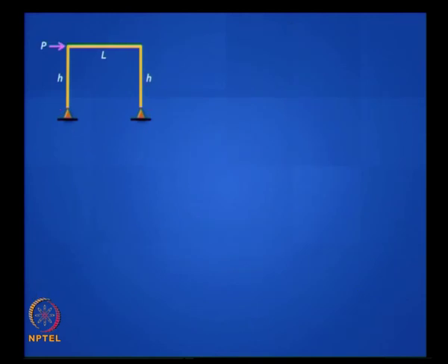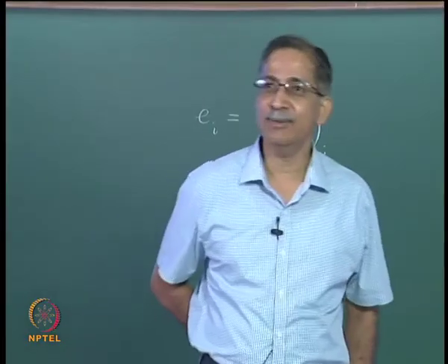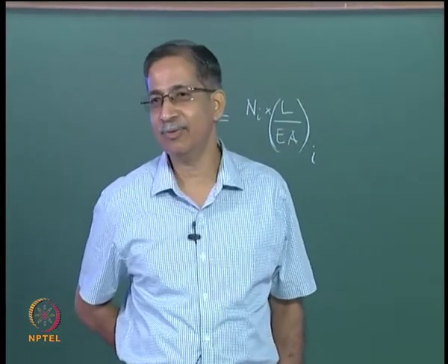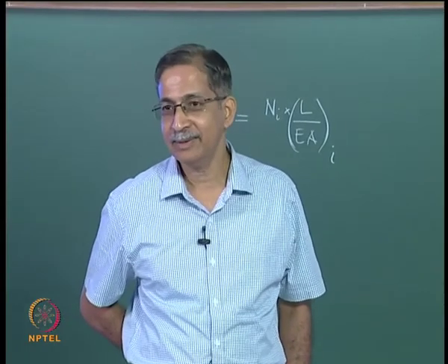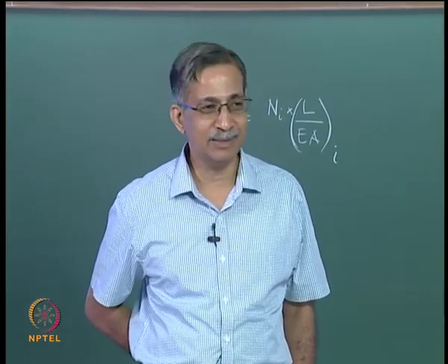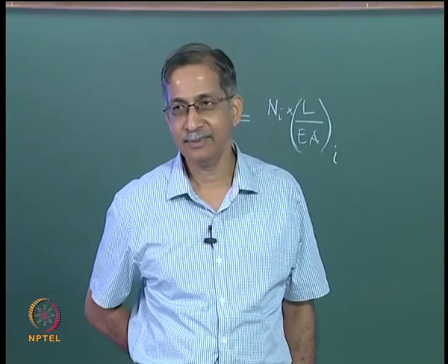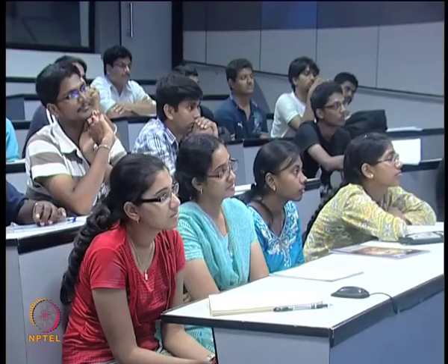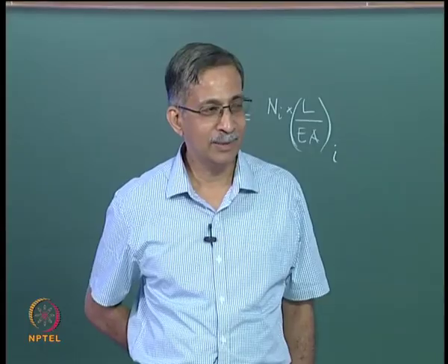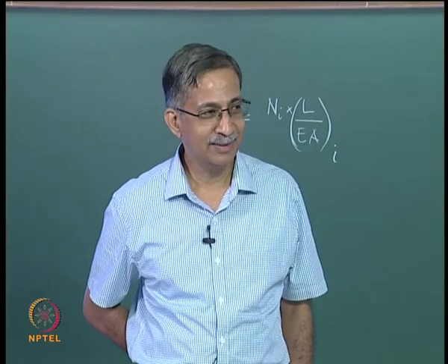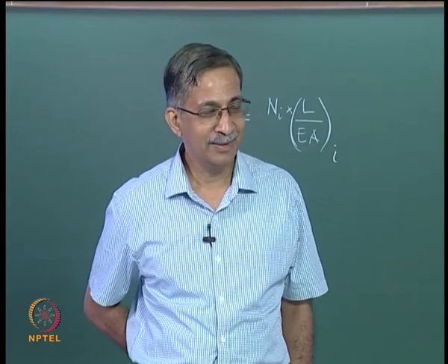One last picture, the last topic. Is this structure statically determinate or indeterminate? This is a frame. It's indeterminate because you have 4 unknown reactions. So how do you say it's determinate? By parity. We separate this into 2 diagrams. Which diagram? Sir, in one diagram P/2 and P/2 forces. Very good, very good.